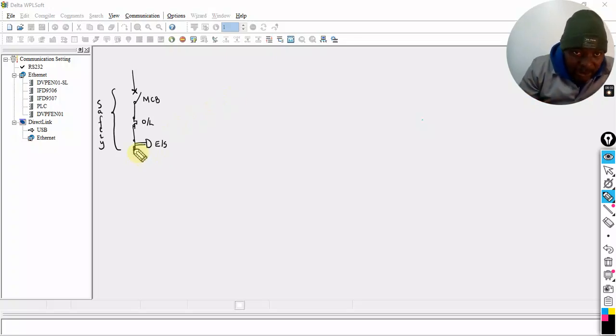Now we go on and say, okay, fine, after our safety, let's operate the machine. Now this is about operation. We need a stop, normally closed, spring back type. You might know different symbols, it's fine. Right, this is the stop.